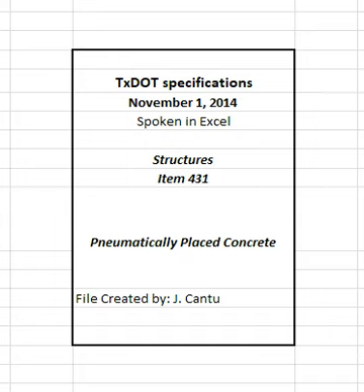Encase reinforcing steel by shooting with sufficient velocity and plasticity that material flows around and behind reinforcement. Apply the concrete using either the wet mix or dry mix process unless otherwise noted on the plans. Mix the materials thoroughly and uniformly using a paddle or drum type mixer designed for pneumatic application. Wet mix process applications can use transit mix concrete. Do not use the wet mix process for repair of damaged concrete.